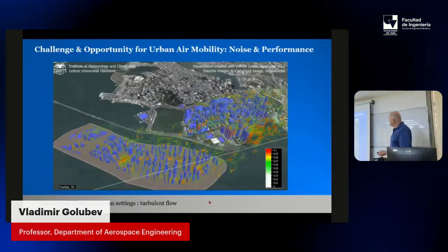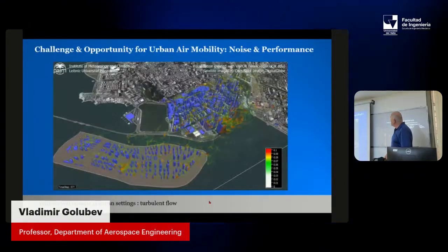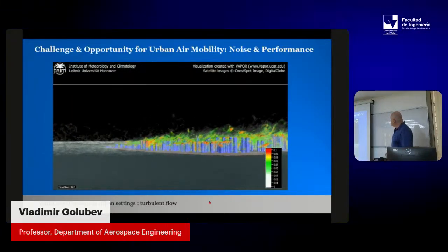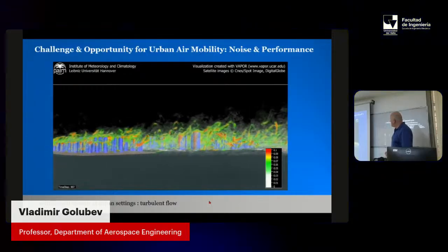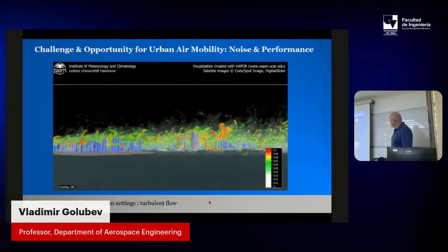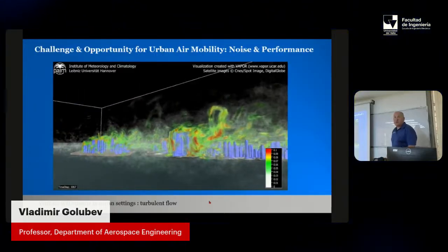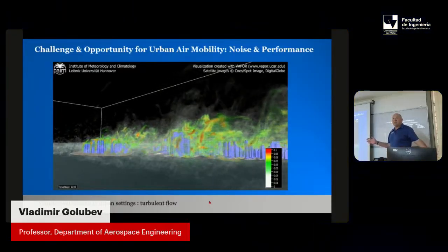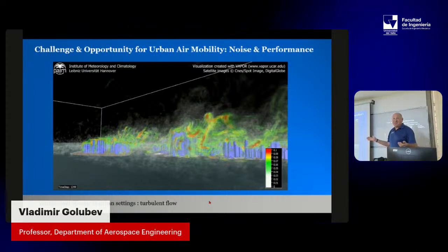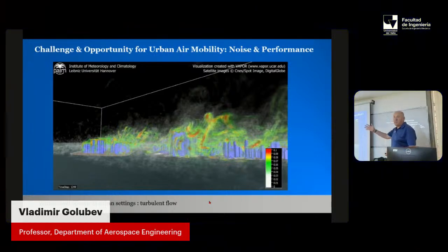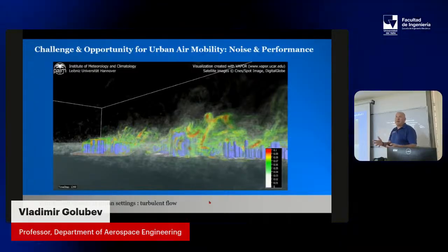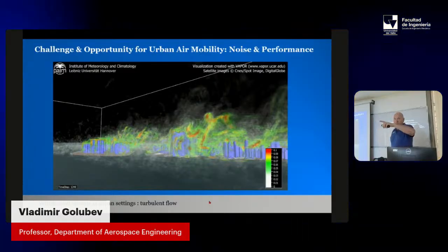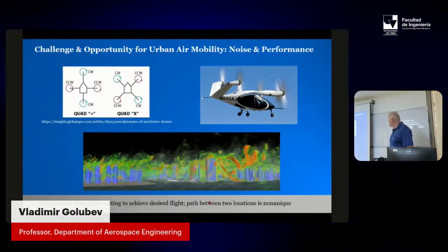We use our simulations, but in parallel, they use what they call mesoscale models, like PALM. PALM is a mesoscale model developed in Germany at the Institute of Meteorology and Climatology, to understand what structures appear around buildings. But for them, the grid size is like 1 meter. You cannot get much from this for our purposes. That's why we get some input from them upstream, and then we run the high-resolution simulations, for instance, to understand what's really happening in the neighborhood of the rooftop.